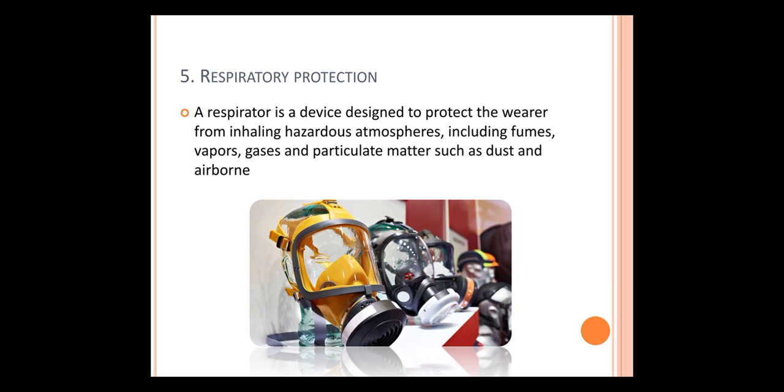Respiratory protection. It is a respirator. A respirator is a device designed to protect the wearer from inhaling hazardous atmospheres, including fumes, vapors, gases, and particulate matter such as dust and airborne contaminants. Respiratory protection is required when engineering improvements and administrative controls cannot eliminate risks.